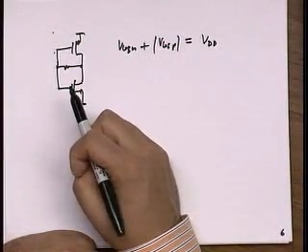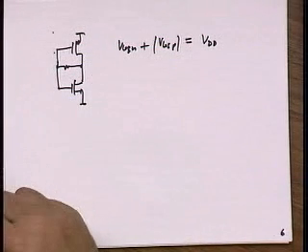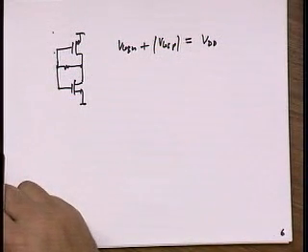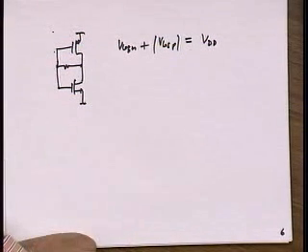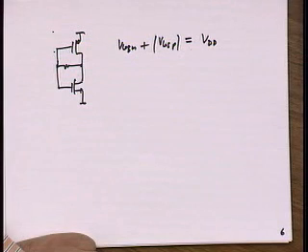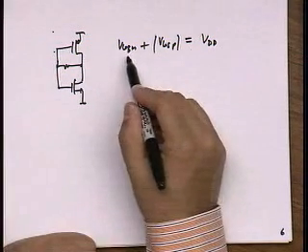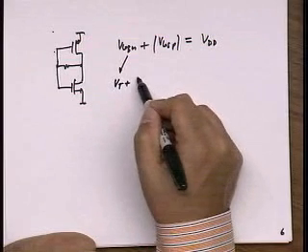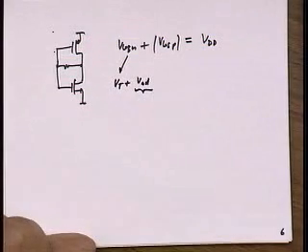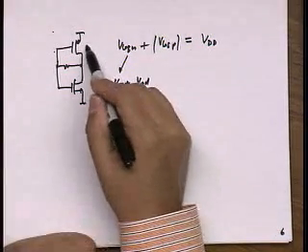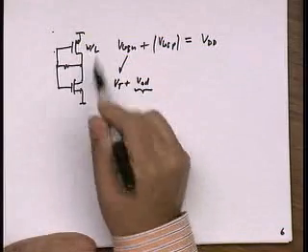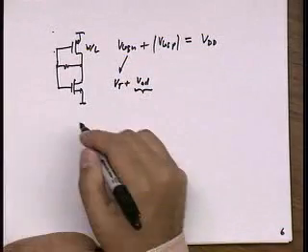And what's the problem with that? I mean, you're making some motions with your fingers. Swing, output swing. Yeah, right. So that kind of goes against our output swing. It means that this is a VT plus an overdrive, and I have to make my overdrives large, right? I'm constrained. The other issue is that if these W over Ls are quite large, this is going to take a lot of static power, right?